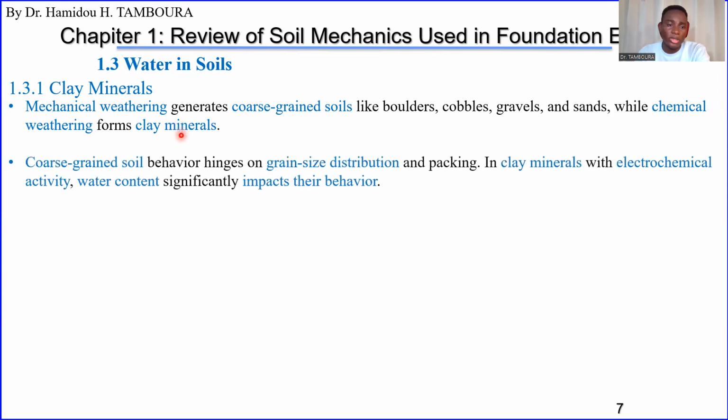For coarse-grained soil, the behavior hinges on grain size distribution and the packing. But clay minerals have electrochemical activity. Water content significantly impacts the behavior of clay mineral. So you should be careful about that.